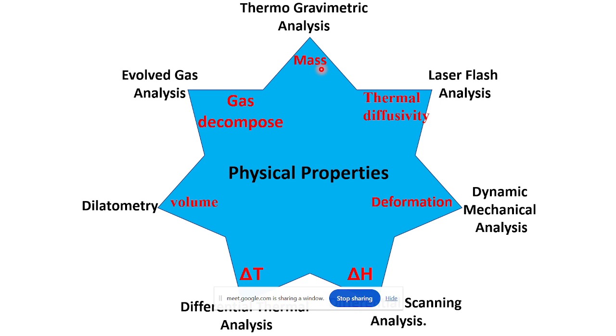Usually for inorganic type material, you will always get a few weight percent remaining even after 800 degrees centigrade. That is because inorganic material will ultimately convert into oxide type products. For example, if zinc oxide is there, it will remain as zinc oxide till 800 or above 800 degrees centigrade. But if there is organic material, for example any rubbery material, after 400 or 500 degrees centigrade, all the organic part will be converted to CO2 and it will be released.